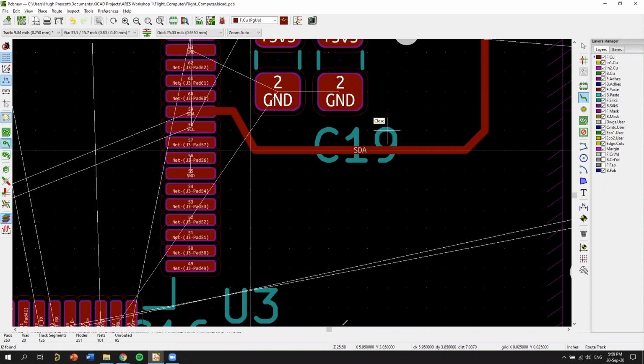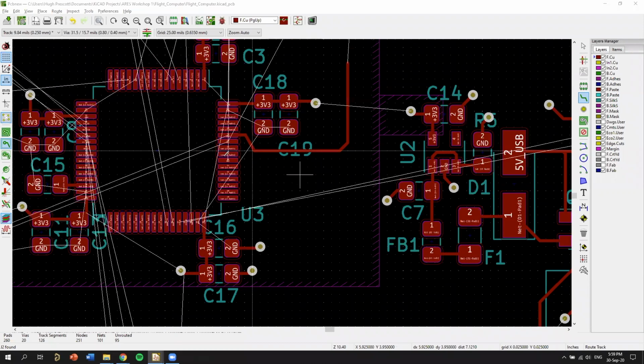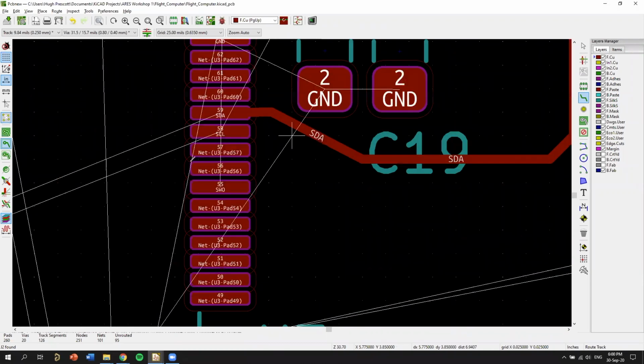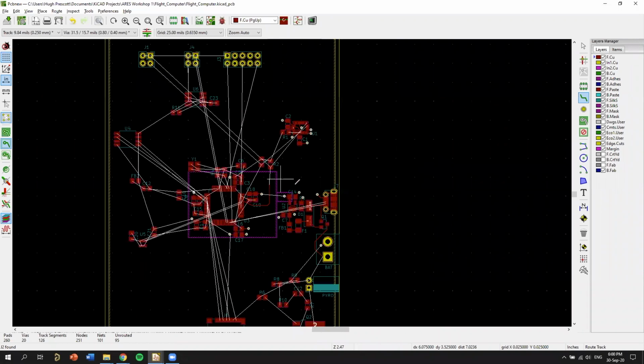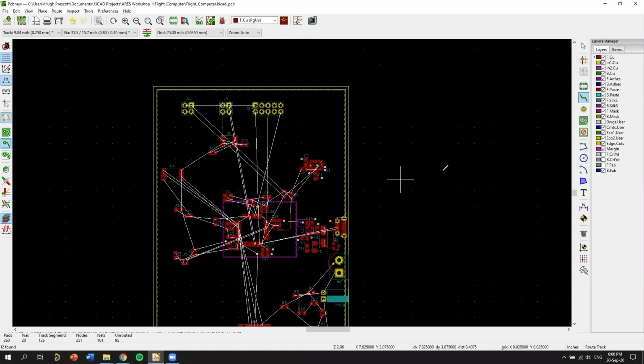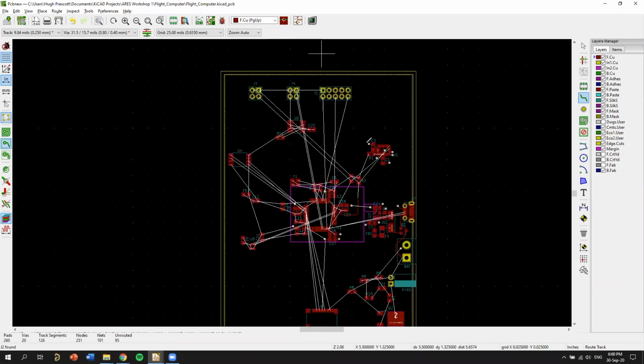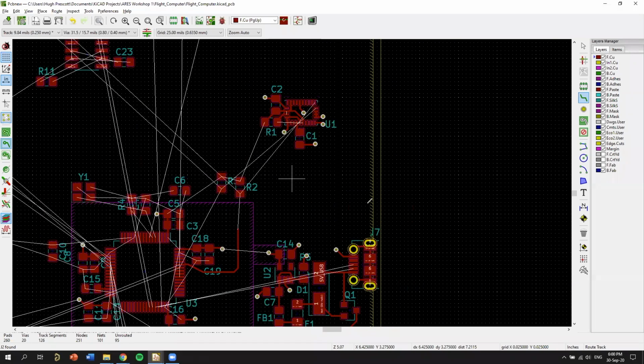Have you seen boards with the ground planes on top and bottom layers? Yeah, normally what they do is, once you're done with your board, they fill up all of the remaining space with ground. It's because the more ground that you put down, the better, really. With asterisks, there are important things you have to consider. If you have too many ground layers, you want to make sure that you stitch them together with vias. It's called ground stitching or plane stitching or something.